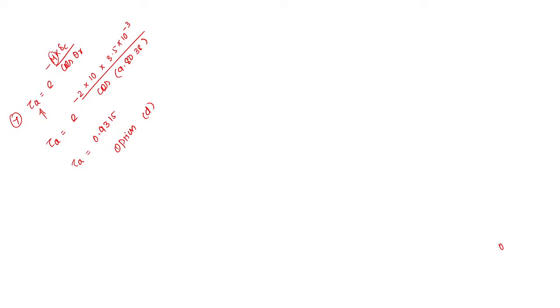And then the 8th one, which is asked as the transmissivity-absorptivity product. So tau alpha is nothing but tau alpha p upon 1 minus alpha rho d. All the values are given, but we are supposed to find out tau. Tau is nothing but tau a times tau r.